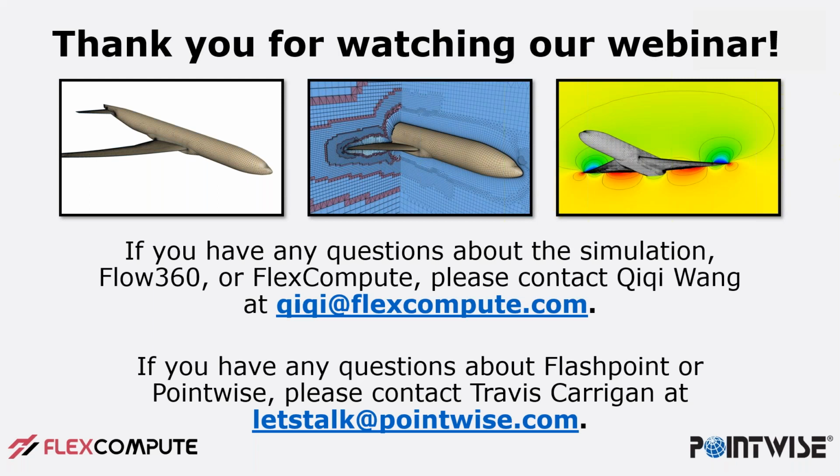Next question: Pointwise for trailing edge meshing, does it need to be blunt, or do rounded trailing edges also get treated in the same manner? Good question. Blunt, yes. We need two convex edges for those boundaries to generate that type of mesh. If it's rounded, then they'll get classified as a curvature type boundary, which is treated differently than a mapped surface.